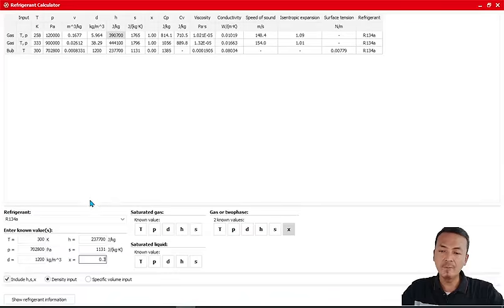And then the pressure after the expansion may be changed into 1.5 bar or 150,000 Pascal. Then you can get the certain value of enthalpy. You need to click the two known values here, the vapor quality, the X, and also the pressure.